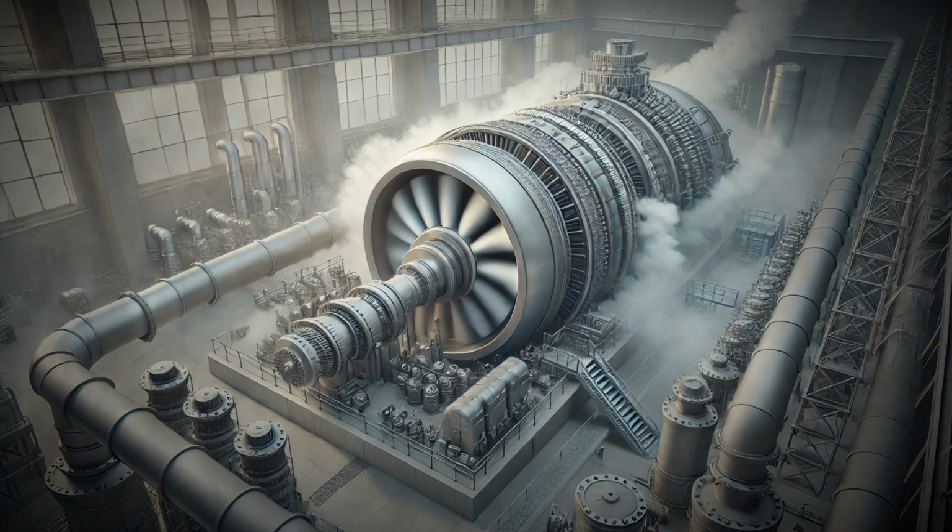Water is heated by the coolant system until it turns into high-pressure steam, and this steam is then directed through turbines that convert the energy of moving fluid into the rotation of massive blades. In pressurized water reactors, the steam is generated in a secondary loop, isolated from the radioactive primary coolant, while in boiling water reactors, the steam comes directly from the reactor vessel. In either case, the production of steam must be carefully regulated to ensure the correct pressure, temperature, and flow rate, because the turbine system is designed to operate within specific parameters.